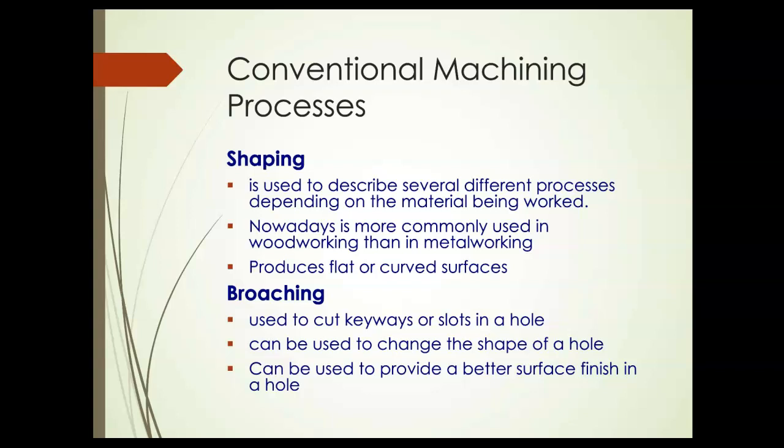Broaching is used often for keyways or slots. We can change the shape of a hole. So if you've got a round hole, we can put a hex broach through that and get a hex shaped hole in there. We could even put a square broach into that and make a square hole out of it as well. So there's a lot that you can do with a broach depending on what you need.